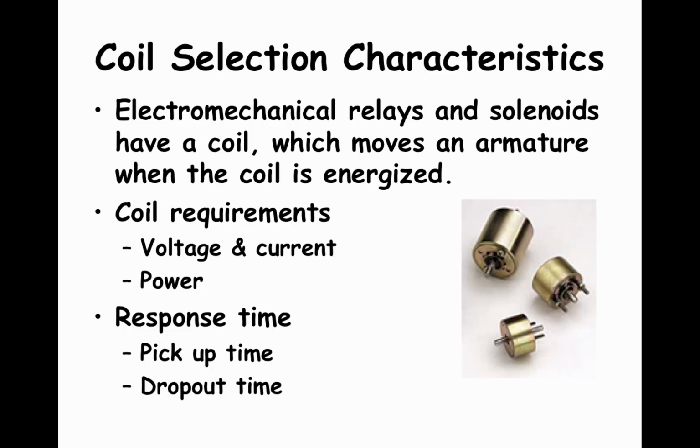Some more characteristics of electromechanical devices with coils are the coil power requirements. These describe how much voltage and current or power is needed to energize the coil. One would expect that larger coils on large magnetic relays will probably need more power to energize them.